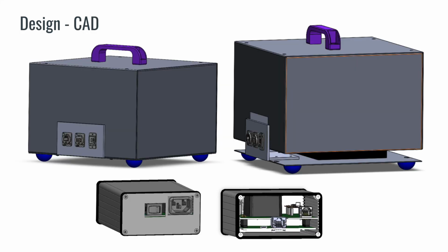In order to eliminate noise while collecting data, an enclosure is used to house the electron tunneling microscope. In order to connect the internal components to the outside electronics, a connect bracket was designed to hold connectors, while also still ensuring the internal components are shielded. Another small enclosure was also modified for the control board and power board, in order for the different connectors and switches to be accessed.